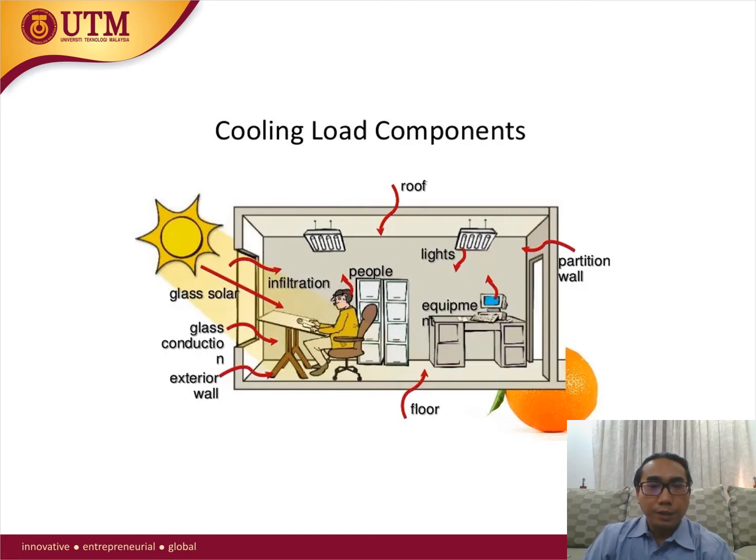As you can see, the figure is an example of cooling load components. The load due to heat transfer through the envelope is called external load. The total building cooling load consists of heat transfer through the building envelope, such as walls, roof, floors, windows, doors, etc. While all other loads are called internal load, such as heat generated by equipment and lights.